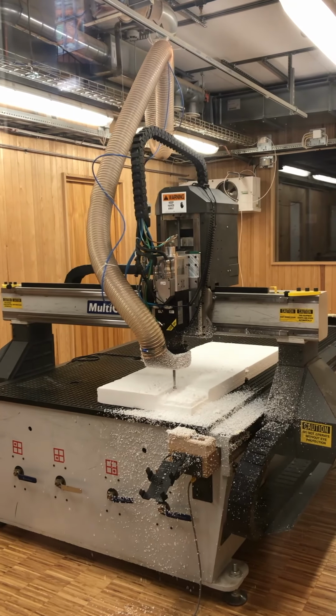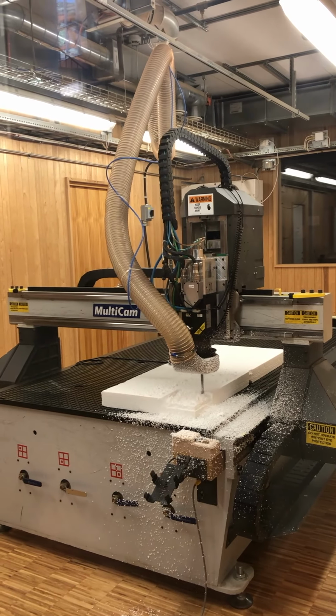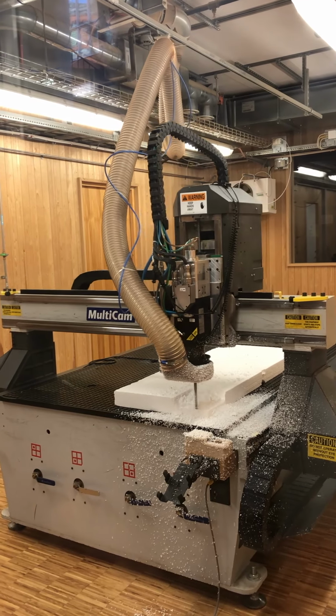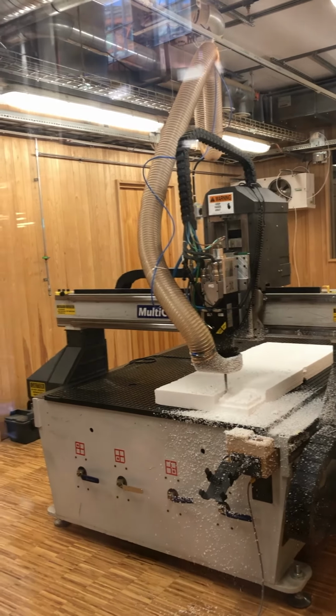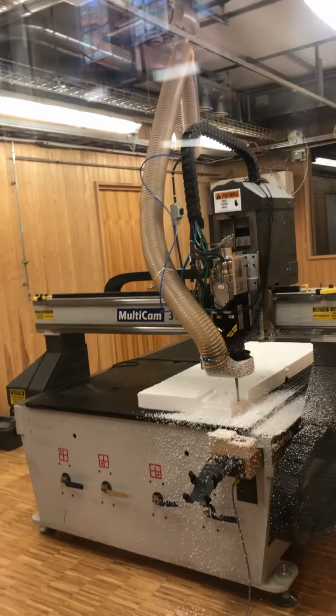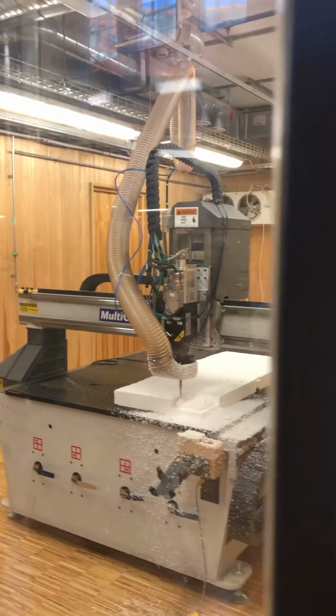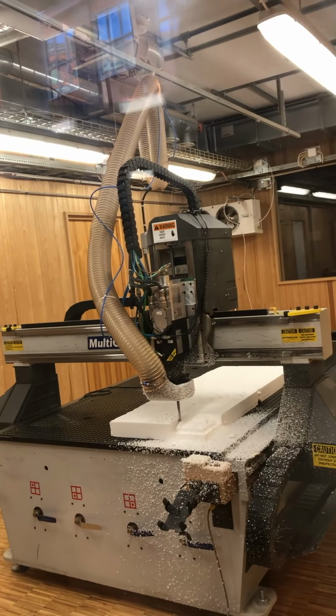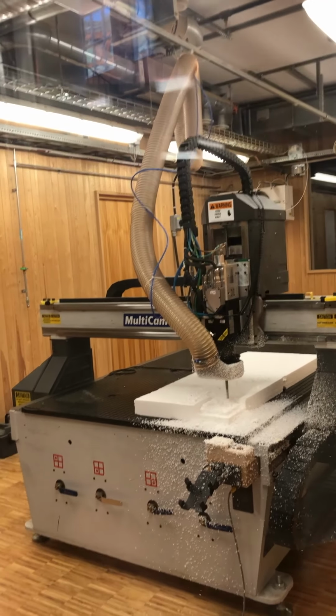If you have set the maximum cutting depth, then it will not extend past that anyway. If you have not set that, then it would extend through the board, and that would definitely break the bit and most probably damage the board or the bed.